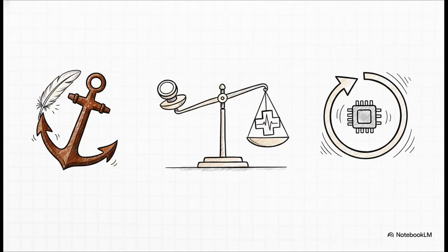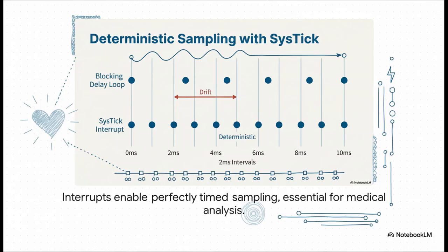And that golden rule helps you avoid some very common and very painful mistakes. Putting heavy calculations in an ISR is a classic rookie error. Another one is something called priority inversion, like accidentally giving a simple button a higher priority than a critical sensor reading. And a really nasty one is forgetting to clear the interrupt flag, which makes the ISR run over and over and over in an infinite loop, completely freezing your device. But when you get it right, the result is just beautiful.